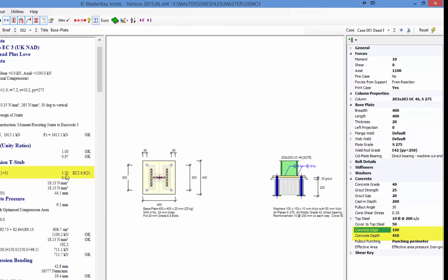Now 1.5 is the normal ratio that you use. But if you know that you've got quite a good edge from the edge of your base plate, technically it will be from the edge of the concrete compression zone, from that point or that point. But just play safe and take it from the edge of any part of the base plate. And I'm going to say that I know I have quite a large base plate, so I'm going to have something around 500 square. So a 1500 square pad, I'm going to end up with 500-600 each side.